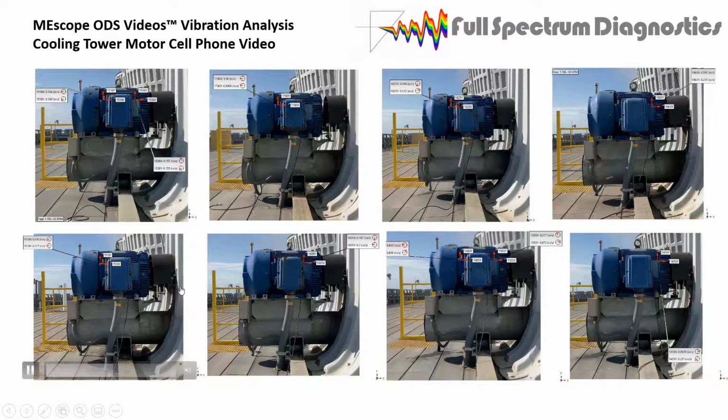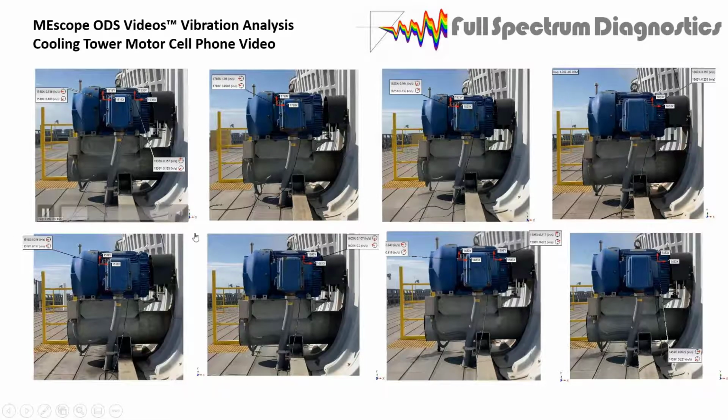Remember, I told you those flat spots on the cowling here are perpendicular to the camera, so they're not going to pick up the XY motion, and you don't have a whole lot of changes. But these discontinuities where the shadows are, that's where the vibration is going to show up. It's the same sort of problem we have here. I tried to pick a spot, and I ended up picking a bunch of them on another view, but where the transducer is, at least 2 of them on the transducer and then another one in here next to it, but this was too flat. This wasn't giving me good results. But regardless, you can start finding out how to best handle the situation.